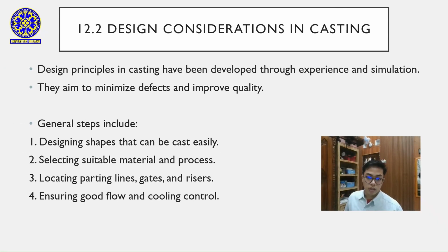Design principles in casting have evolved through years of experience and simulation studies. The key idea is to design shapes that are easy to cast, select suitable material, and properly locate parting lines, gates, and risers to ensure smooth metal flow and solidification.